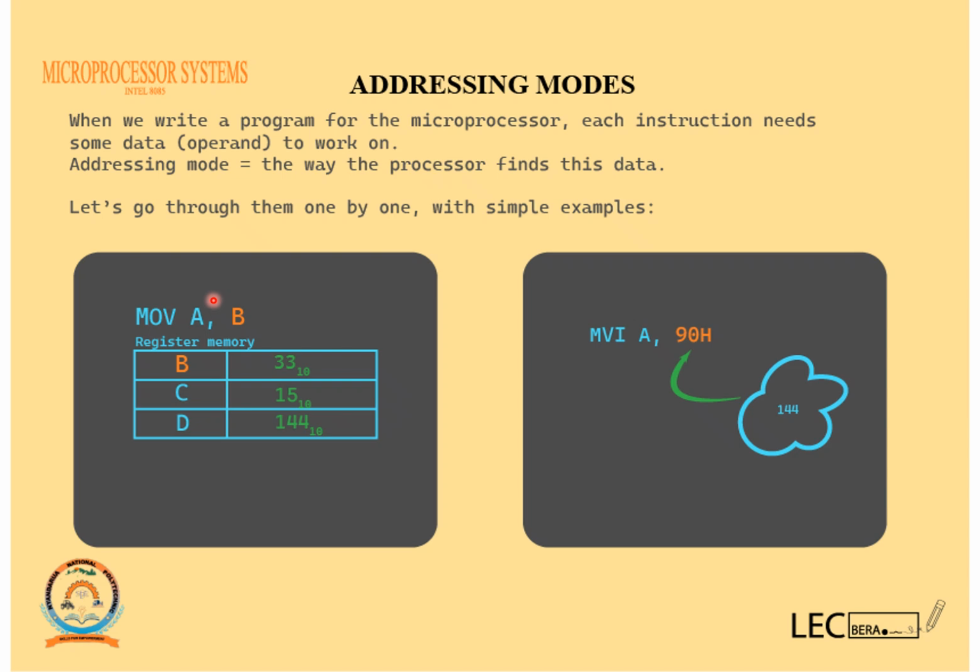So remember, this data, which is the operand, can be inside the register, inside the memory, or inside our mind, your thought. For example, here is a number, 144, which is a decimal number. If I want to insert this data directly into my instruction, then I have to use this type of instruction where I'm going to load this number to the accumulator. Maybe you are now confused.